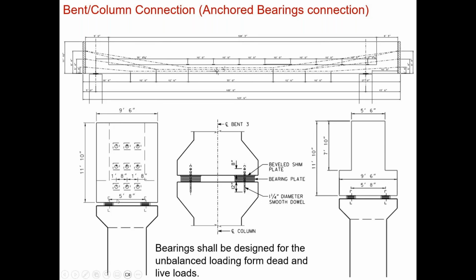And if you look at the out-of-plane view, those bents are typically very wide members. So it is more practical to have two bearings here to support this member rather than having one bearing and run into rotation and stability issues. In addition, you have to think about how the load transfer mechanism happens from the cap to the column. In the in-plane condition, the cap is able to carry the loads and rotate around the bearings and provide full rotation, and there is no restraint or moment that can be transferred from the cap to the column.